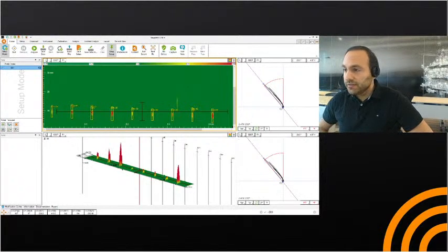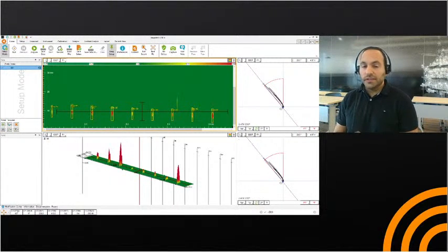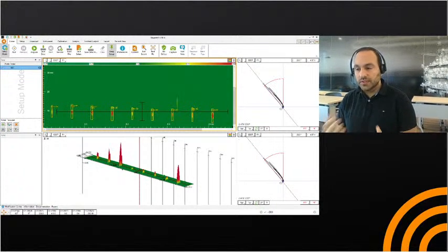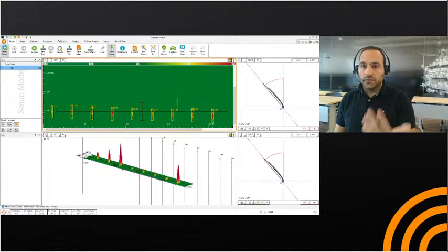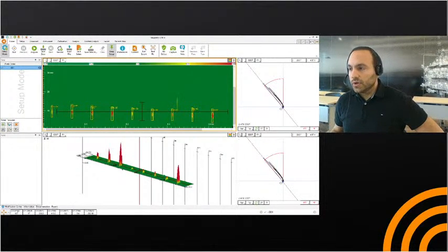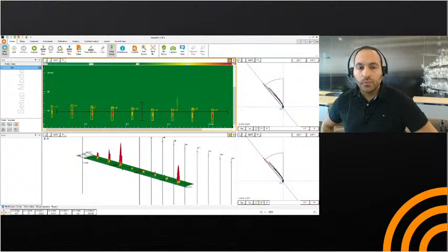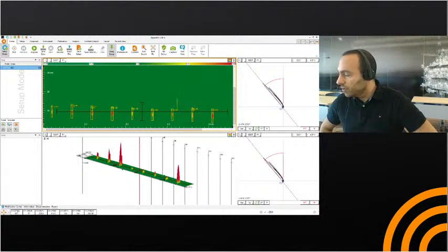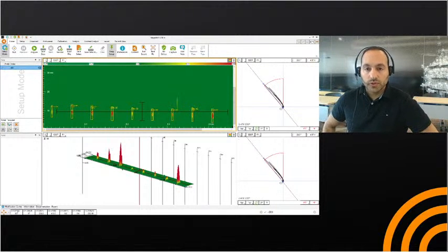Yeah, I actually forgot to mention this. It's always depending on how many samples per millimeter you want to display in your scan axis or scan direction. If you want to have, let's say, 4 samples or pixels per millimeter or more, it's always depending on what you have in hand, but you can go pretty fast with the scanner. You can easily go up to 400 millimeters per second. That's fast for an inspection.